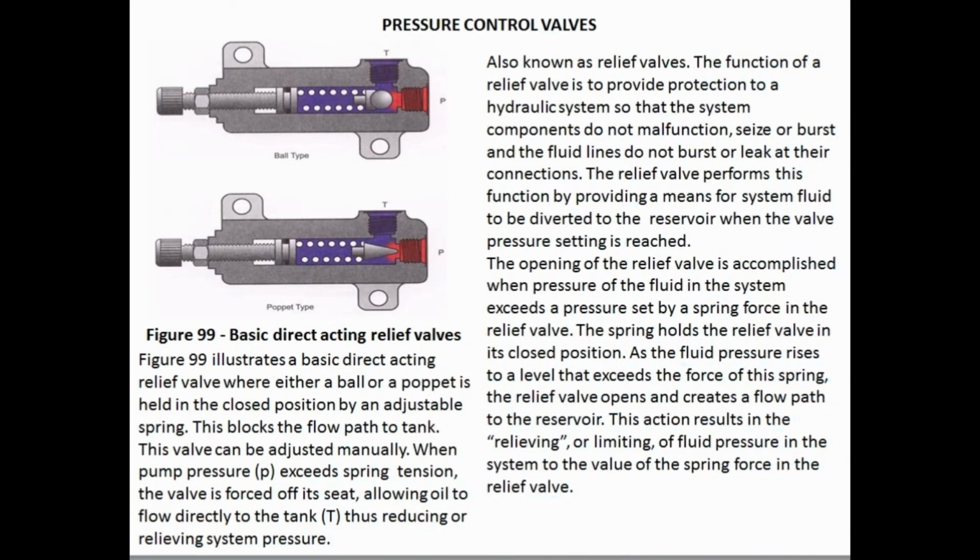Pressure control valves, also known as relief valves. The function of a relief valve is to provide protection to a hydraulic system so that the system components do not malfunction, seize or burst, and the fluid lines do not burst or leak at the connections. The relief valve performs this function by providing a means for system fluid to be diverted to the reservoir when the valve pressure setting is reached.